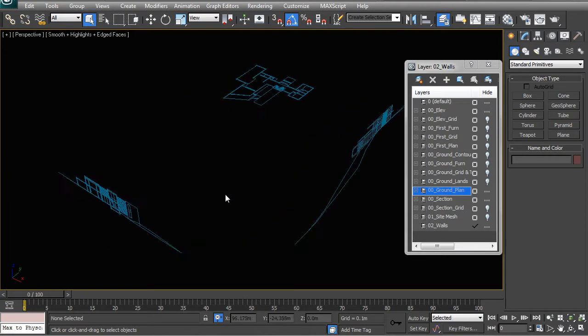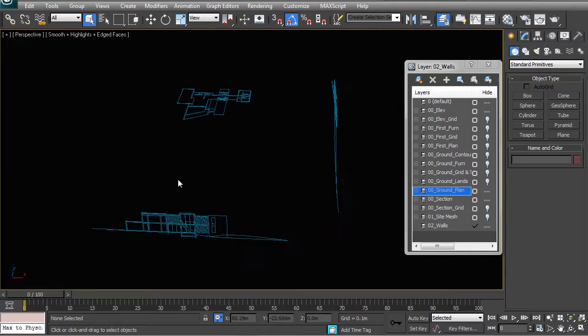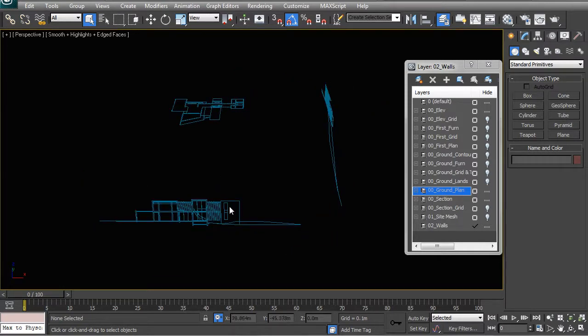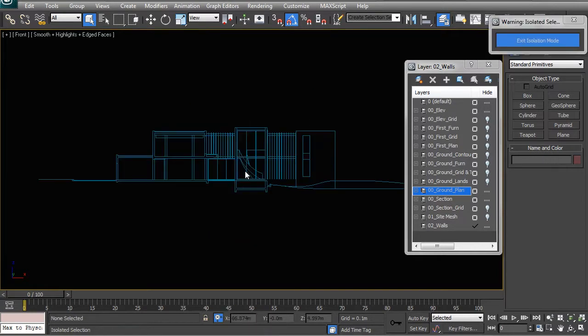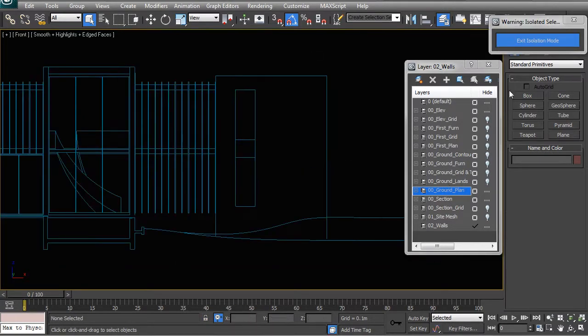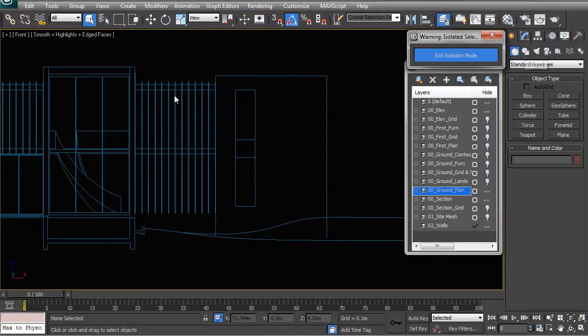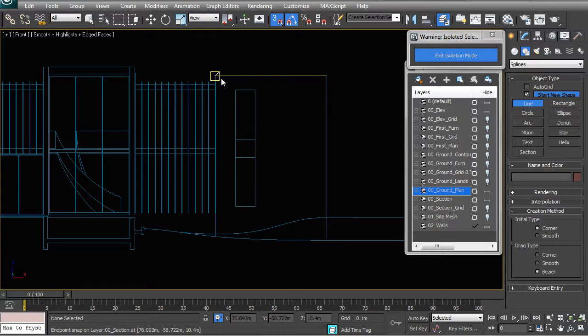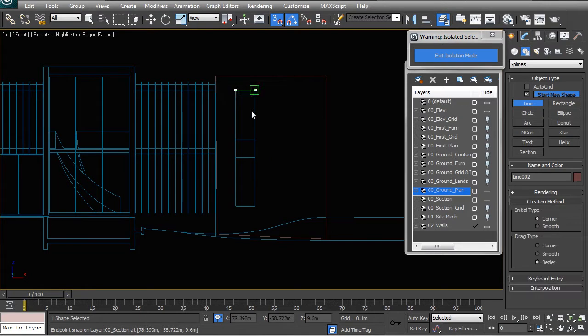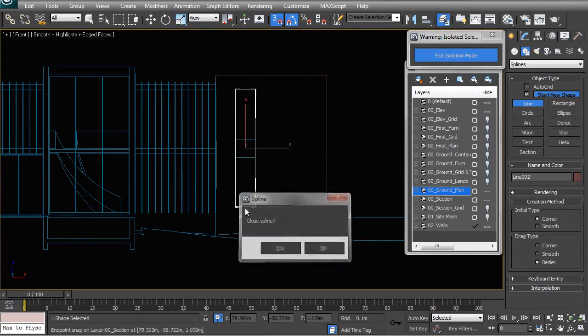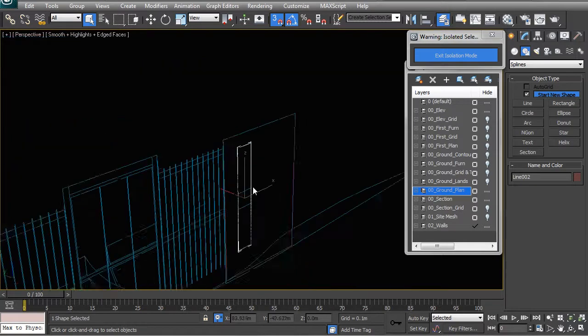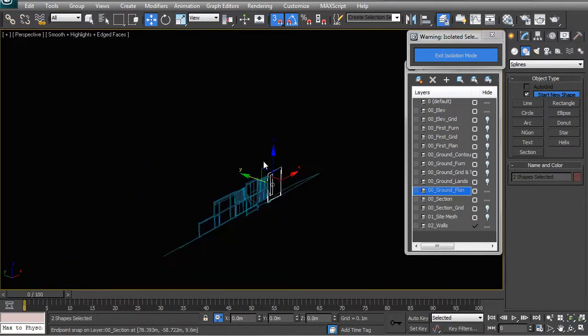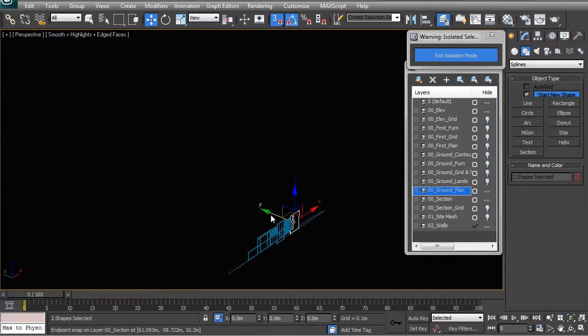Now, already there are a couple of different options. You can start drawing your walls from the plan. There are some people that would go to the extent of drawing their walls in elevation first. So those people may want to go the route of looking at the elevation and then starting to draw the outlines of those walls from those elevations. They may want to draw the wall, then close it off, draw the windows in, and they would basically be creating a vertical object that they would then move into place on plan. Now, this is one method that surely can work,